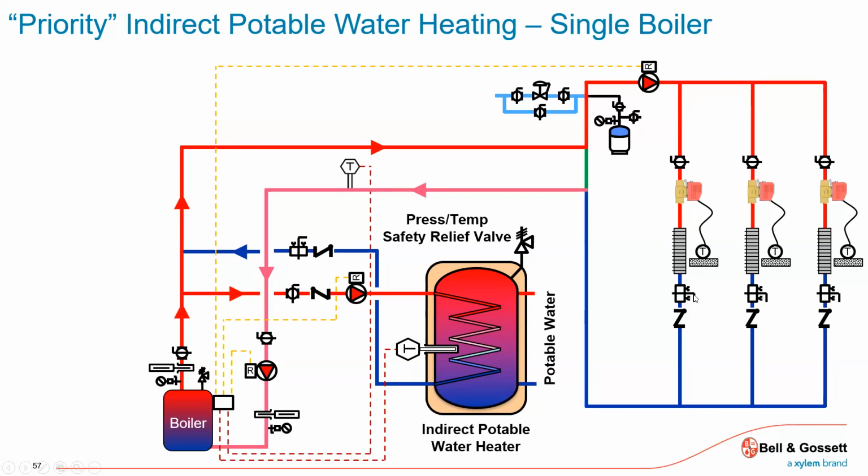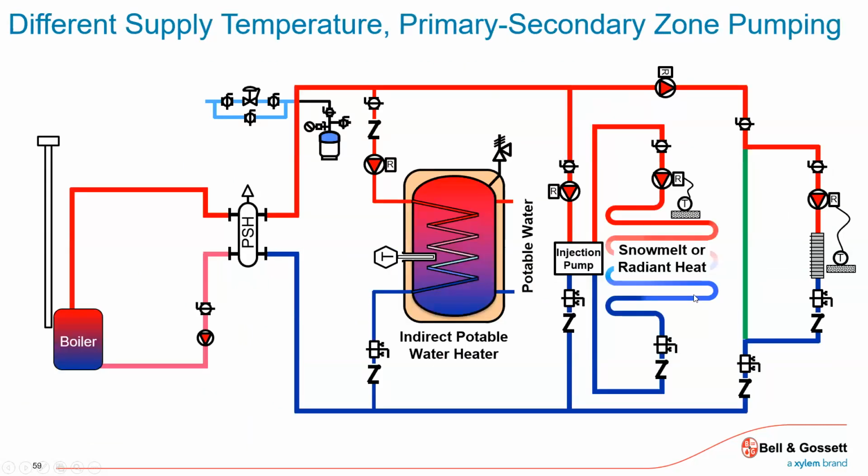So this boiler pump here isn't fighting. It doesn't even know this pump exists. Neither one knows the other exists because they're decoupled right there. It's just an application. It's a way of plugging in using primary, secondary. It could be multiple boilers. You can use it for temperature control.